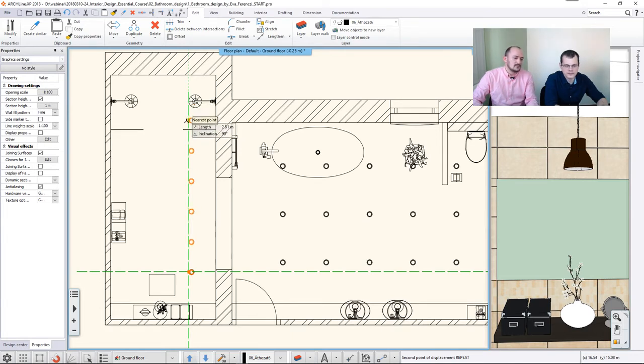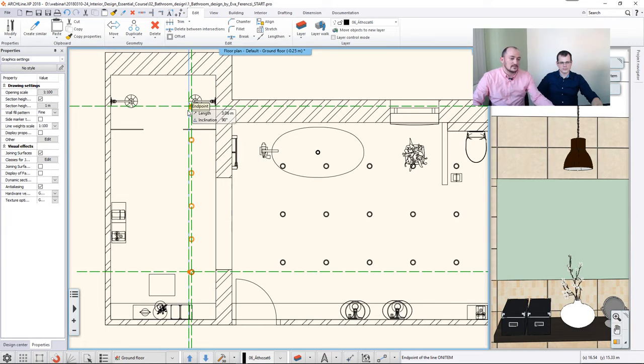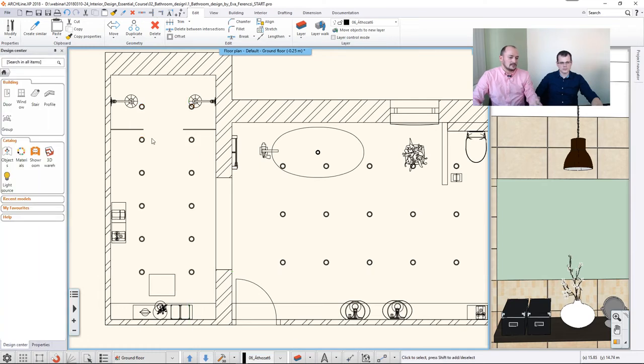Now, a useful thing I think is that there are points that are easily snapped, and this could result in a distortion. I don't want that, so I would like to make certain that it's vertical. So I keep it around vertical, and I just hold Shift. I keep holding Shift, and then I move my mouse, so now it's sticking to the vertical direction as long as I keep holding the Shift key. So now I click again. I can release the Shift key now, and I can just determine where the other is, and this way you can quickly distribute. There is another tool for quick distribution. This is also very useful for all sorts of objects as well.